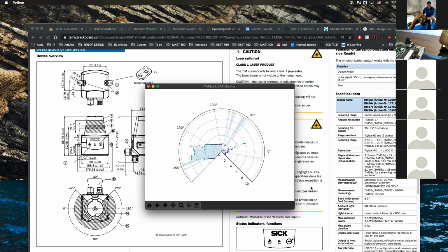There are other surfaces, like a mirror. A mirror can reflect points away so that they never return to the lidar, so the lidar might return either a 0 or a very far distance for those surfaces as well. As you use the lidar, you'll notice that things that absorb light very well will give you really poor readings, and solid walls will give you great readings. So as you make scans of stuff around you, be aware of where you might be getting funky readings, especially if your Scuttle is going to be making decisions off of this data.